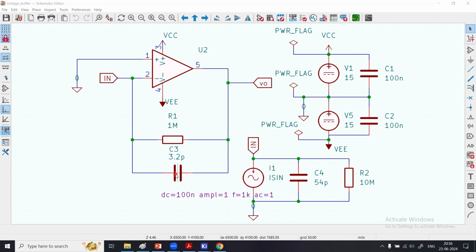Capacitor is there just to provide the stability, and thus prevent the circuit going into oscillation. So it's just there to provide the stability, and we would see it would act as a linear current to voltage converter with a gain given by the resistance. These are the power supply symbols we explained. Now look at this, where this current can come from.